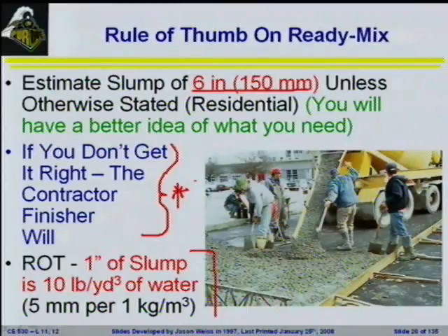On residential construction, don't the concretes there experience less strain? It's usually wood construction over it, and not as much loading anyway? Well, it depends what it's designed for. This is where we come back to: if it's designed to be 4,000 PSI concrete, then you should know that you've got 4,000 PSI concrete. If it's 1,500 PSI concrete, then it's 1,500 PSI concrete. In residential construction, strength is generally not the main limitation. It's usually going to be a durability problem that pops up, or a shrinkage problem.